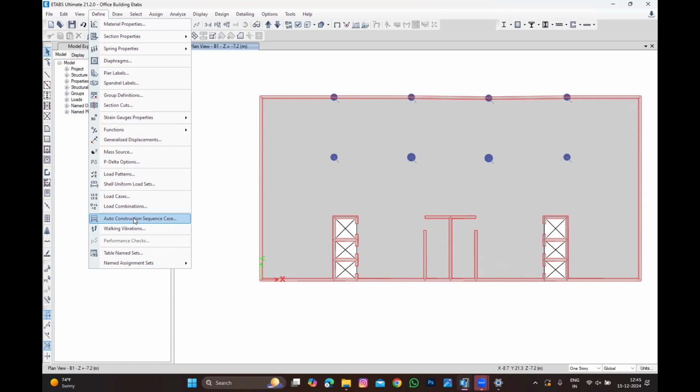The maximum creep coefficient is 2. But between these two only it is going to play: 1, 1.1, 1.2, 1.3. It is very simple, I'm telling you. You are going to reduce the modulus of elasticity of concrete by having some reduction factor. That's it. The modulus of elasticity is what? 4,700 multiplied by root of f'c.